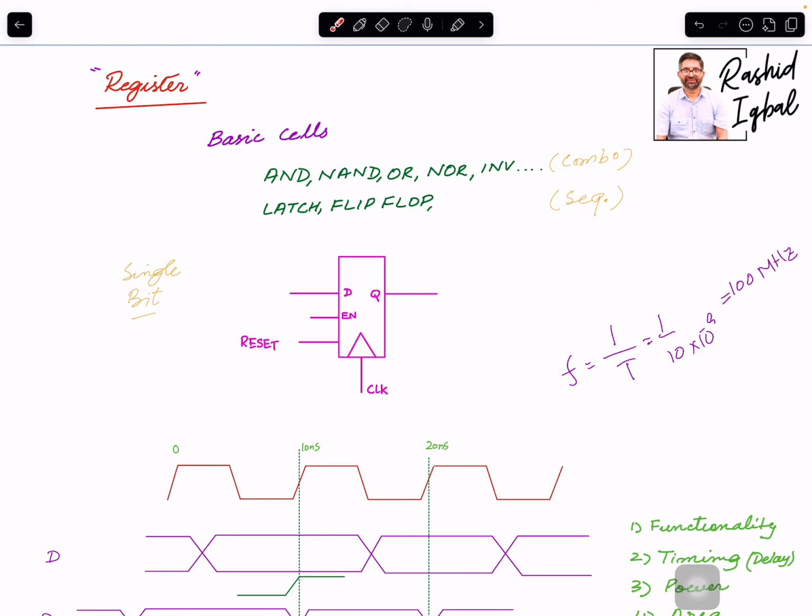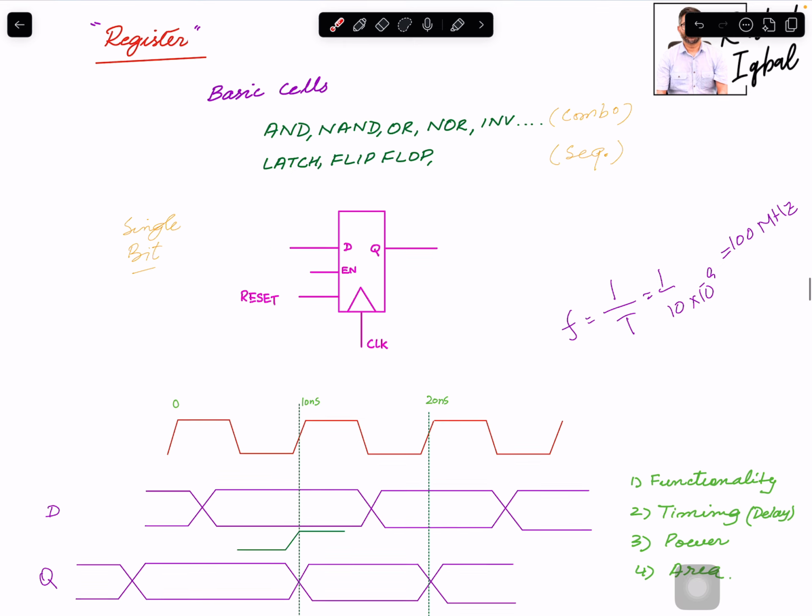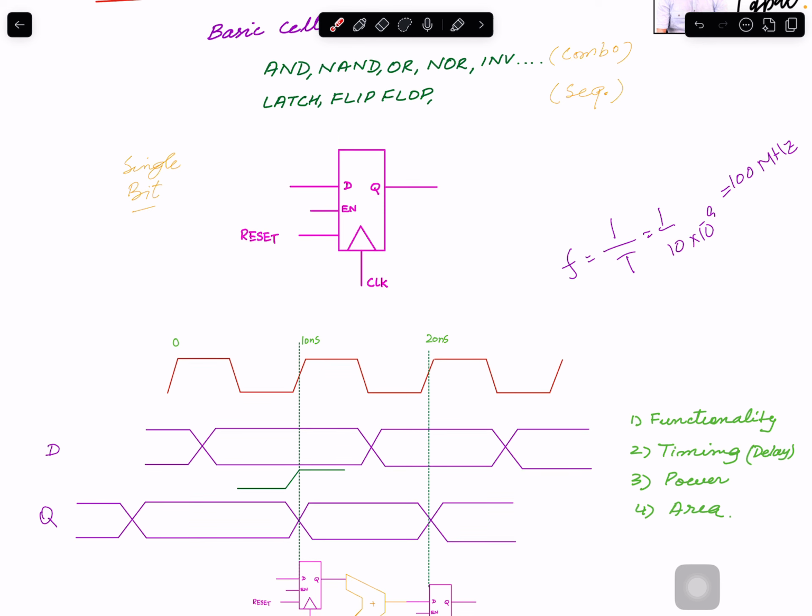Okay, why do we need a sequential cell? These are the storage elements, also called sequential. Why are these sequential? Because through them we can give a sequence to a lot of operations. If every operation starts happening at the same time, we cannot put any sequence to it, and then you cannot do the useful work. In order to do the useful work, we need to bring the notion of time sequence, and that's where the clock comes into action. So on all these storage elements or sequential elements, we have a clock connected.